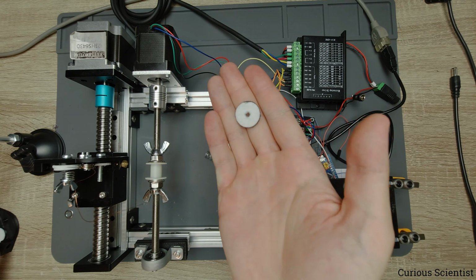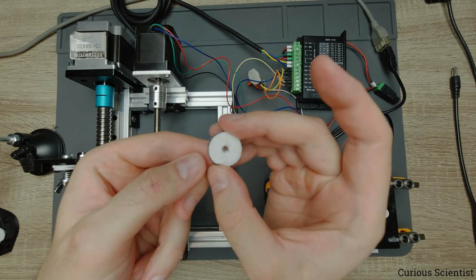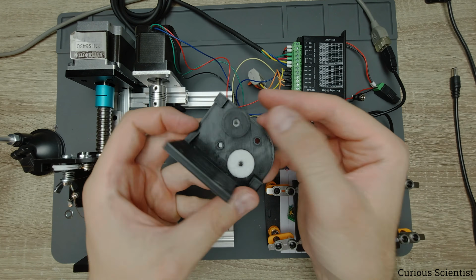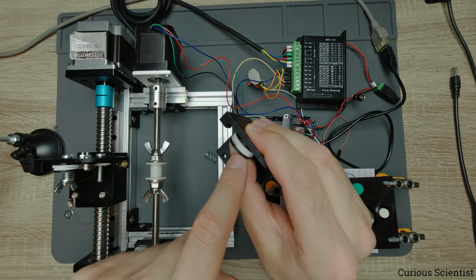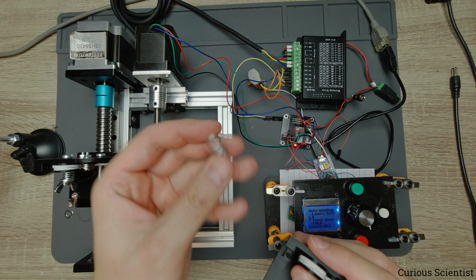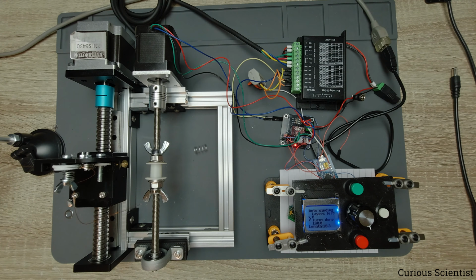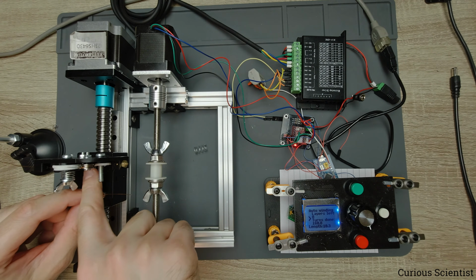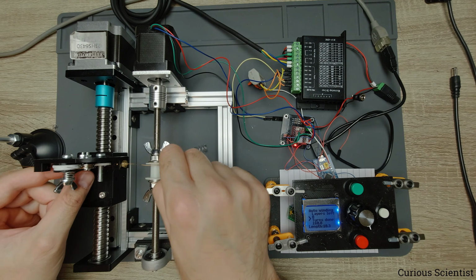So this is the small felt disc. So this is a 2 centimeter 3D printed disc, and then we just have this self-adhesive felt. And actually how it works is just we have them sandwiched together, so it goes like this, and then the wire is in between these 2 discs, and we compress it by turning the nut against this spring. So it's not too much compression, of course, and not too much friction, but it's enough. So now I have the other bearing, and then I come through the nozzle as well.